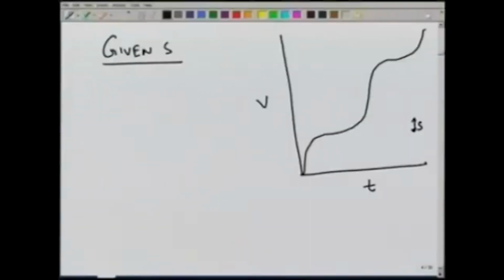Draw lines, let us say at the ridge at some point Q1, such that our demand here is met by storage of S. This S is known to us, so it will give us an idea about what is the Q which we can maintain for this S. Similarly, from here, if we have certain S, what Q can be maintained? Let us call it Q2, and so on.